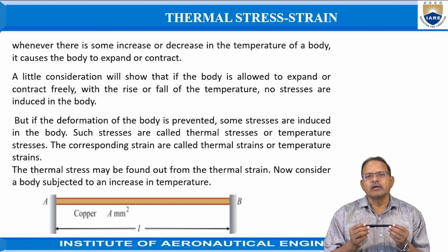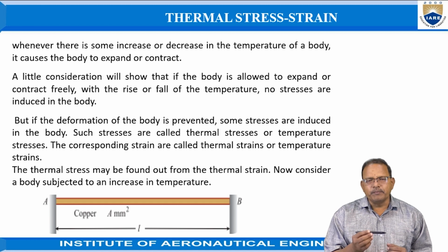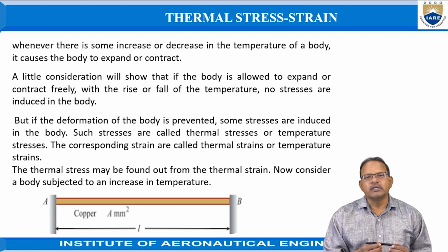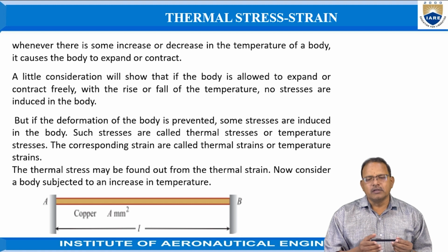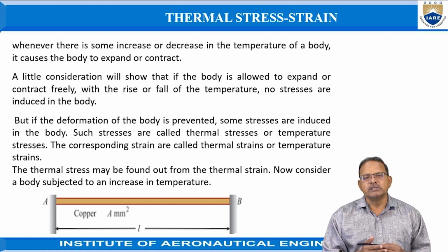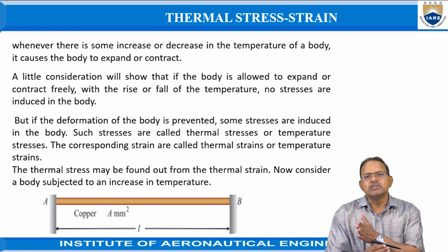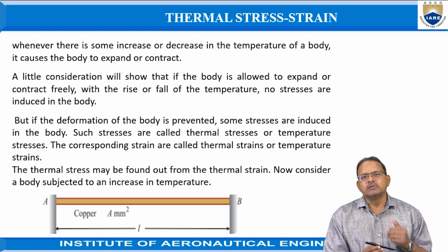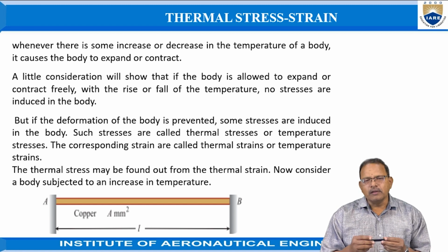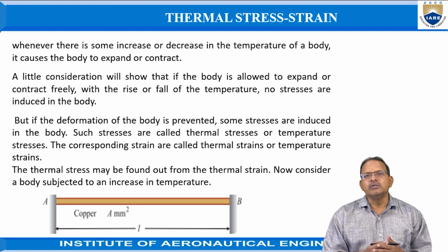Here I am taking an object. Just assume it has 100 mm length at 0 degree centigrade. When the temperature of the object is raised to 50 degree centigrade, generally the length of the object increases. When it is allowed to increase its length freely, without any supports to prevent its expansion, there are no stresses induced in it.